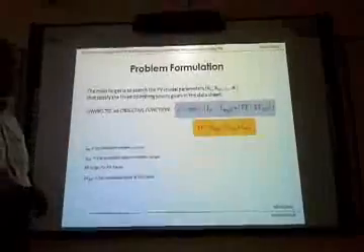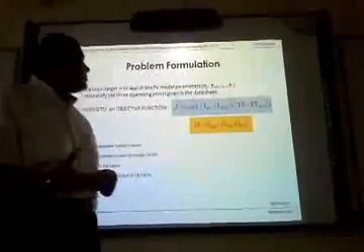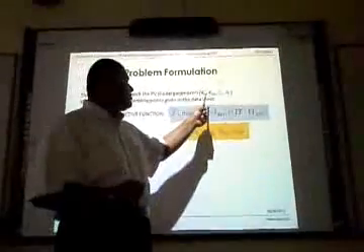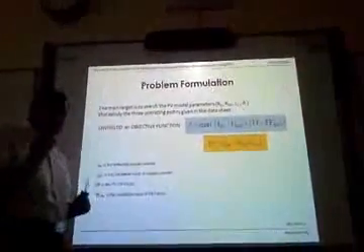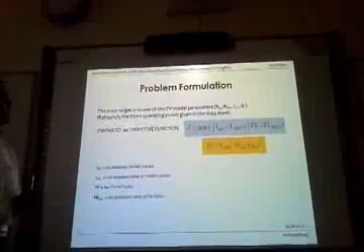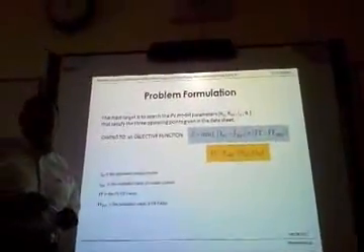Problem formulation. The main target is to estimate the optimum values of PV module parameters: series resistance, shunt resistance, I0 and A, that can satisfy the operating point given in the datasheet. To do this, we select a suitable objective function.